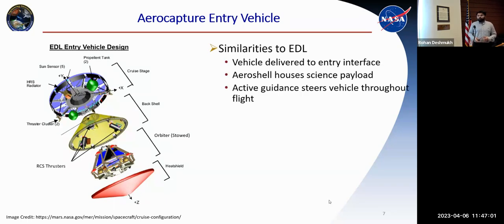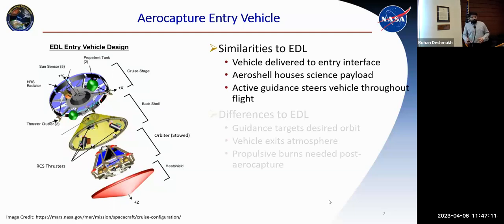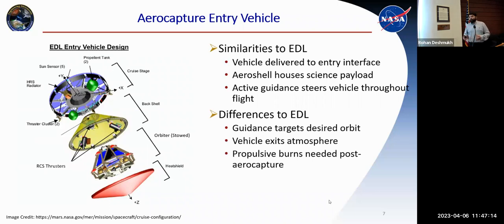So in general, there are a lot of similarities to EDL when it comes to the vehicle and aeroshell design. In fact, a lot of the subsystem-level technologies are shared between Aerocapture and EDL. Now, of course, there are some differences. Aerocapture is not exactly EDL in the sense that we're going to exit the atmosphere. There are different conditions that guidance would target. And of course, you have to carry some propellant on board to do propulsive burns that you wouldn't do for an EDL mission.